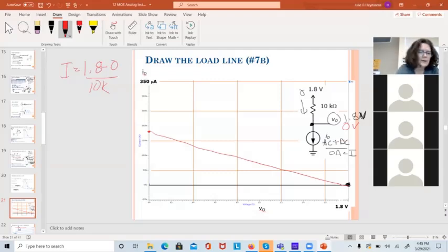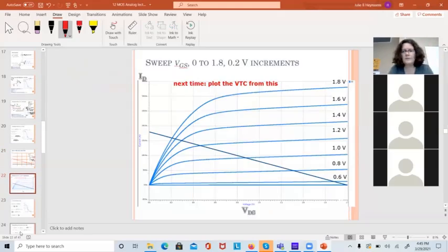So my operating point, because of the resistor, has got to fall somewhere along that line. Now, remember, if the transistor is behaving like a transistor, it's going to be operating along one of these curves. There's a halfway curve, like at 1.7 volts in between here. And we can put the load line across the transistor curves and pretty quickly determine the minimum voltage to keep it in saturation.